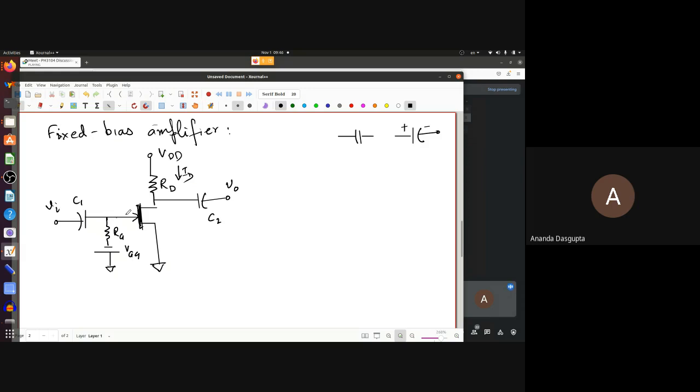So the frequency we are dealing with is large enough that we can treat these capacitors as shorts while not worrying about the other capacitors in the circuit at all. Not capacitors you can see in the circuit, but other capacitors between wires, and between the gate and the channel. These are stray or parasitic capacitors. We are not going to frequencies so high that they will be effective. They will essentially have infinite impedance in this case, so we will just ignore them.